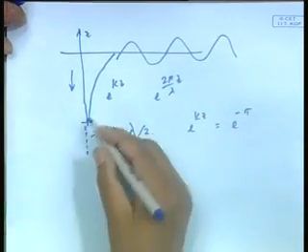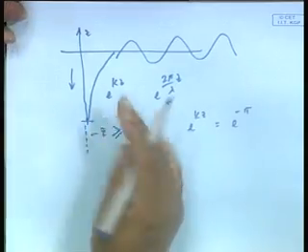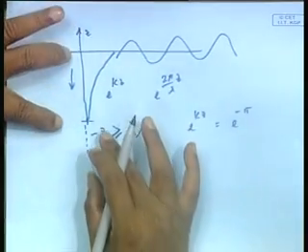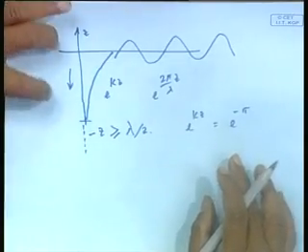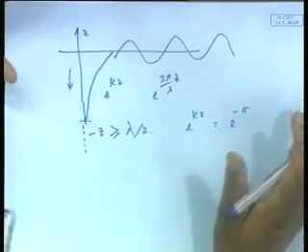On the other hand, if the water depth is less, of course, that would not hold. In fact, we call that intermediate water. Now, why am I saying this? Because in our course of seakeeping, we normally always deal with deep water cases. Why? Because a typical wavelength would be about 100 meters, 200 meters, 300 meters, maybe 400 meters. But ocean depth, where ships operate, runs in thousands of meters. So, mostly the operation of a ship would be in deep water. Therefore, in the rest of the course we will only consider deep water cases, because ships operate in deep water when we are looking at ships.